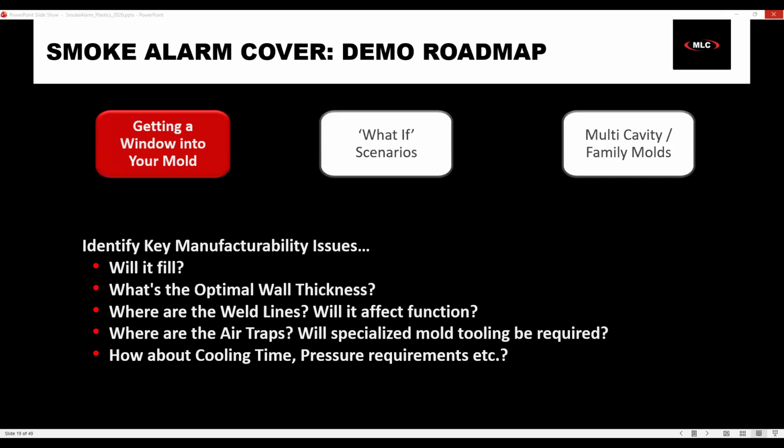Another tool that you have is inside of the actual boundary condition. Right now, this is the feature where this injection location is set, and it is just working off of a simple 1-point sketch. So you can choose just geometric points. This is a sketch because it's right in the middle of something. But over on the left here, there's an item that says predict fill pattern.